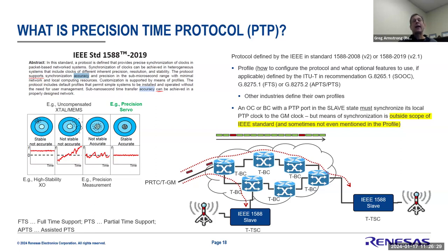And then you can get very precise measurement, right? I could use PTP and tell you exactly when you transmitted and exactly when you left, in accuracies of nanoseconds, even sub-nanoseconds, but it may not be very stable. Because what if I'm using one of those uncompensated oscillators to try to stabilize the clock? Well, it's always going to be drifting on me every time I recorrect it. So how do you get stable and accurate?